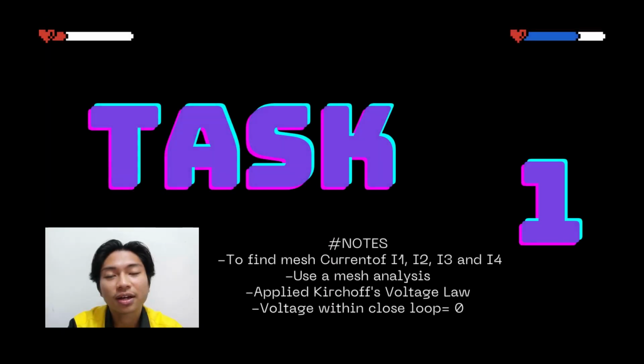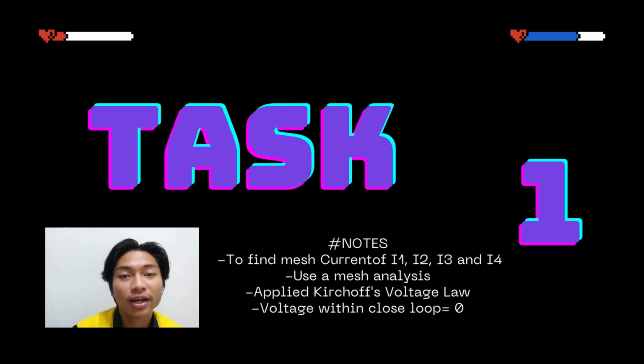Next, I will explain the calculation at task 1, but for question 2. For question 2, the question asks us to find the mesh currents I1, I2, I3 and I4 by using mesh analysis. Mesh analysis is a method to calculate a current in a loop form. So for mesh analysis, we apply the KVL, which is the Kirchhoff voltage law.